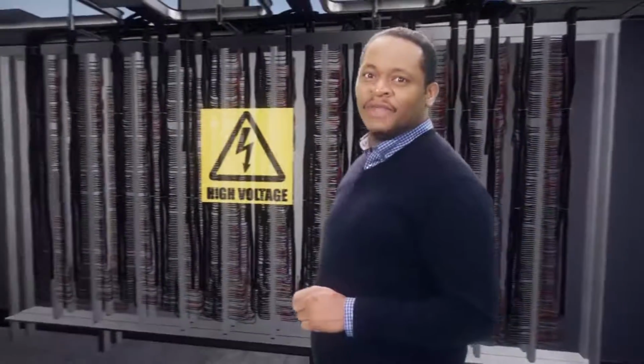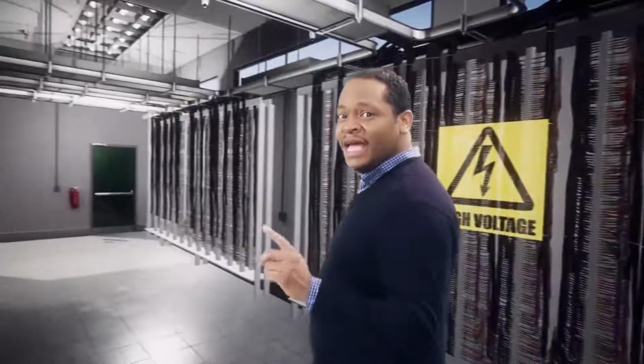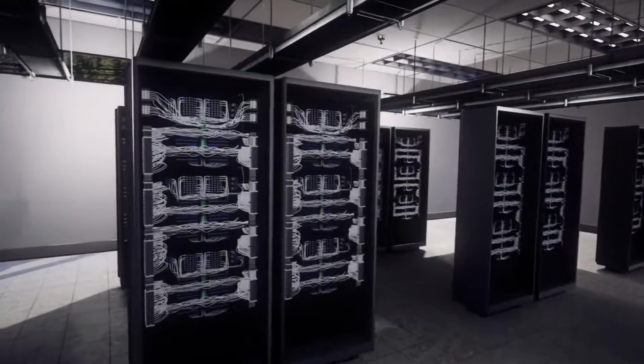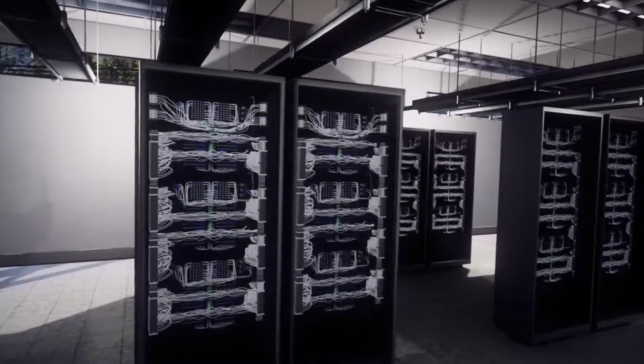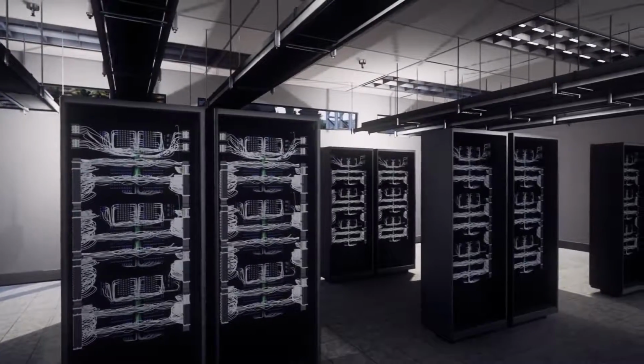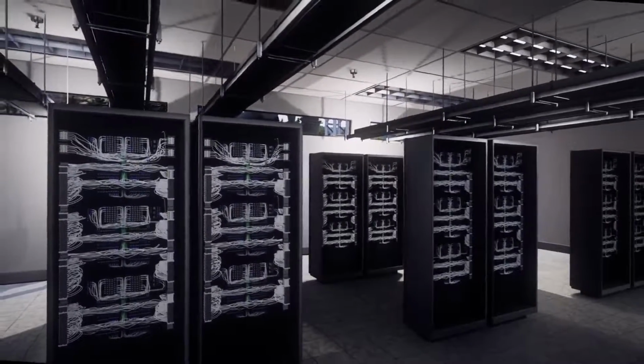In this conventional relay room, all of the wires from the switch yard terminate on these racks before they are connected to the protection and control devices there. There are literally thousands of terminations that need to be made. Again, think about the complexity and labor required to design, commission, install, and maintain all of these wires. Let's see how this changes when we convert to digital.